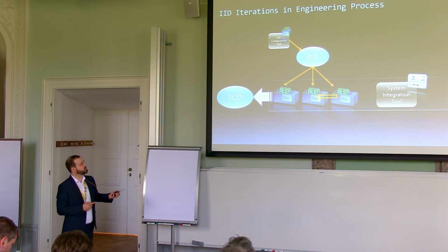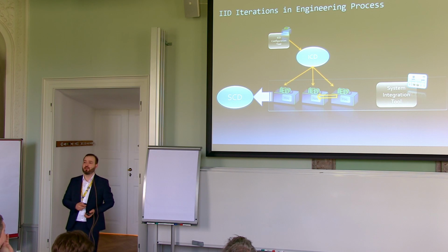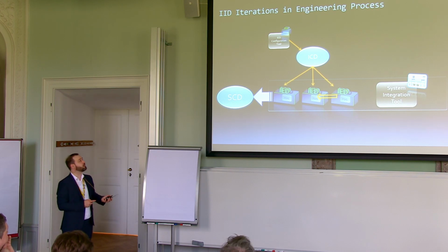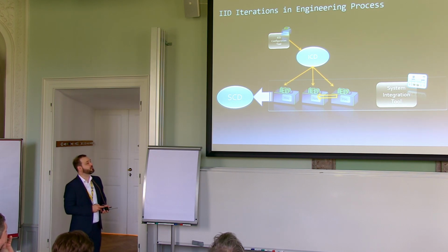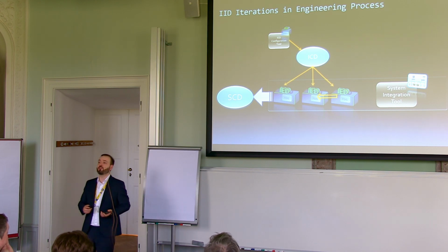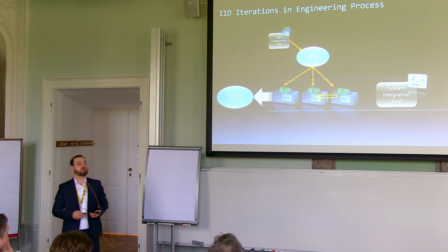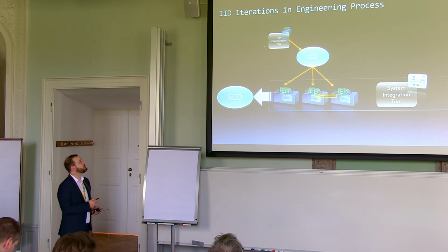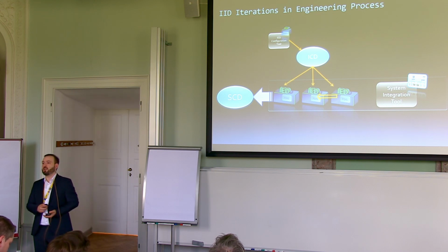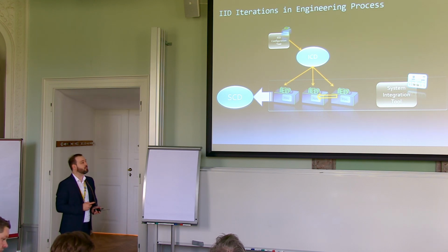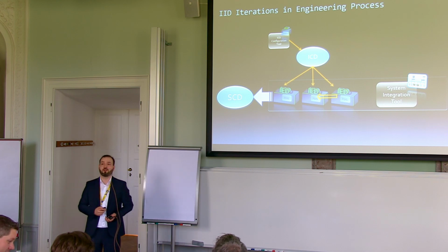Now, what happens if we need additional parameters? There is a logical node missing, or maybe there is a data attribute missing that we know the relay is capable of, but it's not in the ICD file. Well, in that case, we need to do some changes. What we could do is go back to the IED configuration tool and get an improved or better suited ICD file.